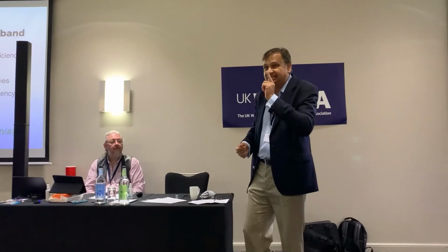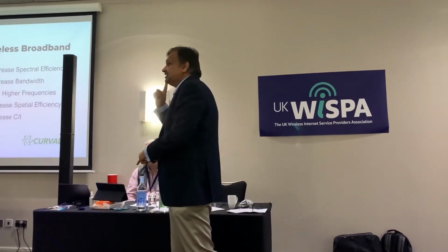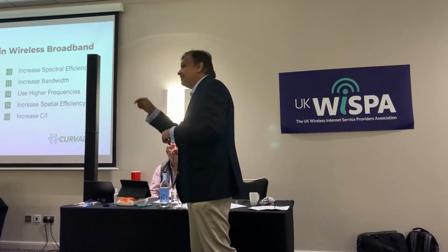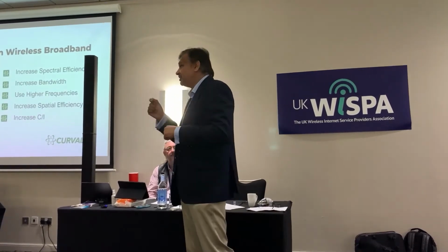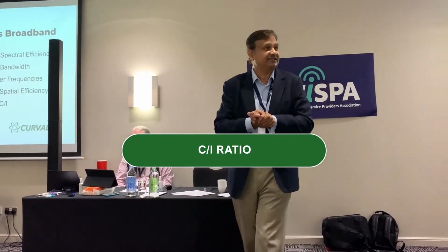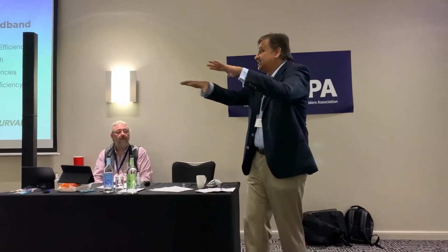Why? The reason is the higher modulation increases the spectral efficiency, it increases the capacity, but it does not increase the availability of the capacity. And people are not interested in capacity, people are interested in the availability of the capacity. The dollars come from the availability of the capacity. And on what factor does availability of the capacity depend? That depends upon your C/I ratio, carrier to interference ratio. Because the moment you go for higher modulation, your system gain reduces. You become more vulnerable to interference. And if you are working in an environment where there's already a lot of interference, you may not be able to use those higher modulations. So all the benefit has gone.